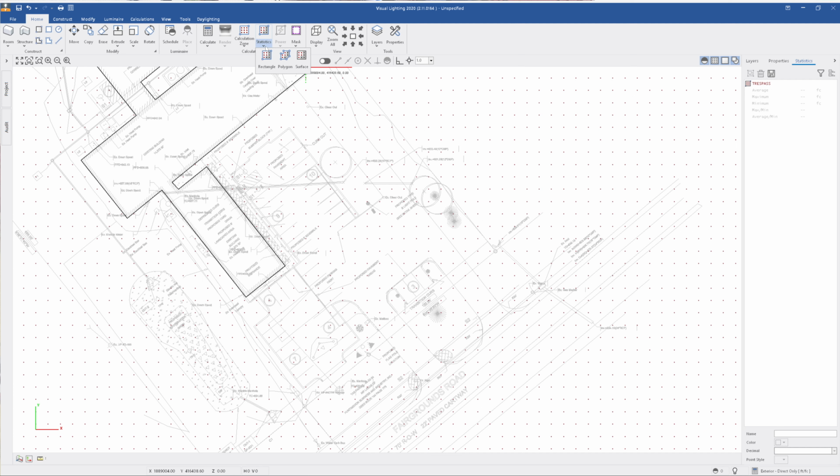One good thing to remember, though, is that it only calculates on the grid points. So you can have a break in your calculation zone in between grid points, and it's not going to be referenced. You may see some of your lumen foot candle contours broken in those areas. So I try to minimize them, but that is one thing that you can always remember to try.